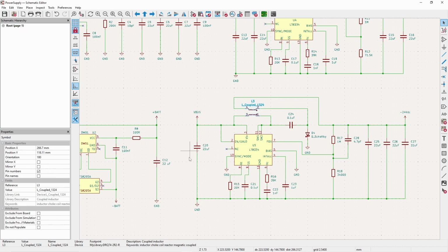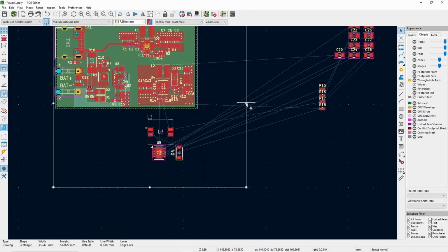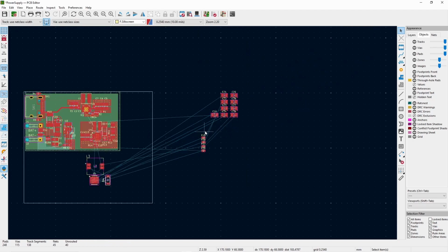and then we've got some of the functional components on the bottom. So soft start, frequency timing, things like that. So I'm going to arrange it in roughly this layout on the PCB design. As I said before, getting the component layout right makes the tracking a lot easier.